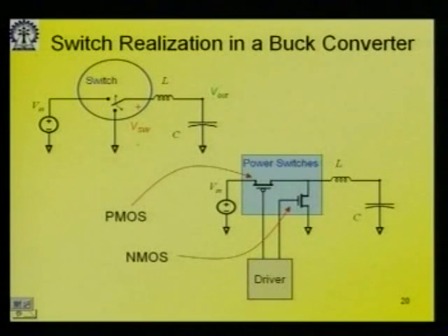Those of you who will be studying electrical engineering will be coming across power MOSFETs. You will see that there are 2 types. One will be these laterals that we are talking about in on chip realization, and the other one will be so called vertical power MOSFETs, which are used for say 100 volt, 200 volt, 400 volt kind of devices, and which have much larger breakdown voltage and much larger capacity.